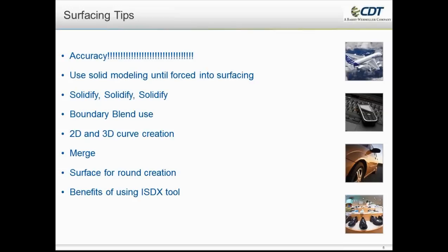Also, what I found with more surfacing and curve and merging and solidify work is that when you go into regeneration failure towards the top of your model tree, anybody that's ever noticed this, you get a domino effect of failures, and it just kind of rolls on you, and you'll sit there for a good part of the time fixing failures, especially when you have a lot of curves and boundary blends that you're creating. If you were to create some solids, sometimes you get out of those situations. So this is more of a talking point than anything else, but again, if at any point in time you get into some surfacing situations, as much as possible, use solids until you are forced to get into surfacing.